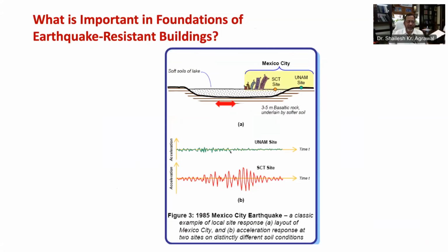Let's conclude it now. Amplification of ground motion depends on soil properties, which comprises of its shear modulus, damping, soil layers and their properties, saturated versus dry soil, loose versus dense soil. It also depends on ground motion characteristics. In general, stiff soils have lower amplification while soft soils higher. Seismic design codes provide response design spectra for underlying soil strata for different soil types.